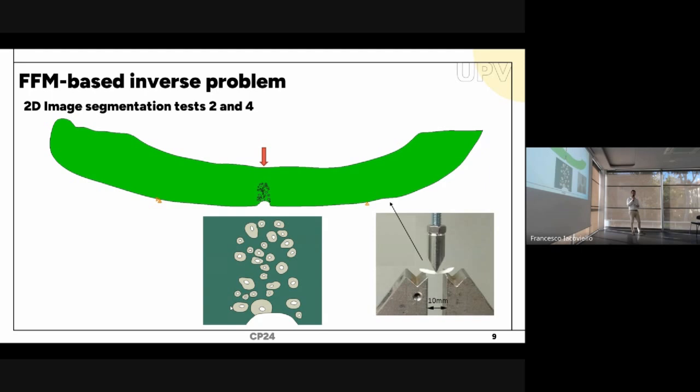We used image segmentation near the crack propagation zone in order to obtain the osteons in gray and the interstitial bone in green. And far from the zone, the material was homogeneous. Here, we applied the load at which cracks started propagating during experimental testing in order to obtain the right point where crack propagation onset occurs.